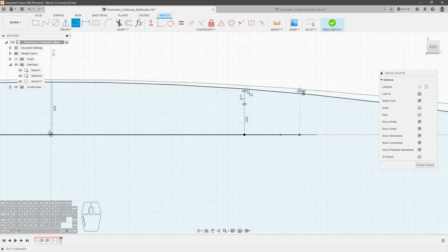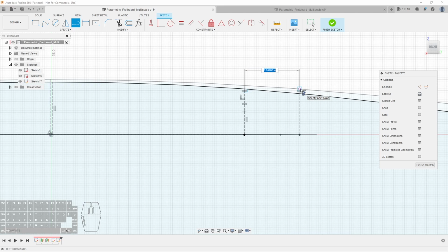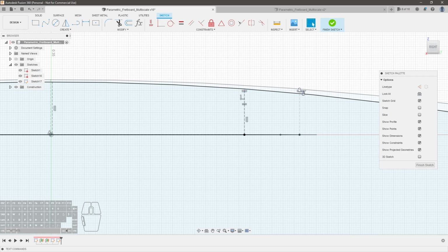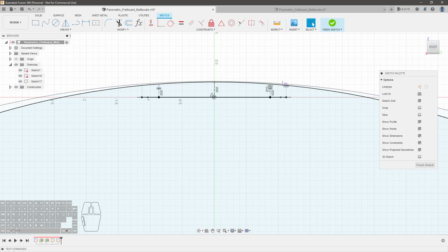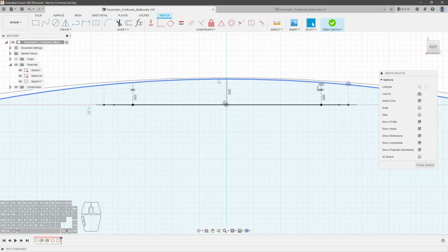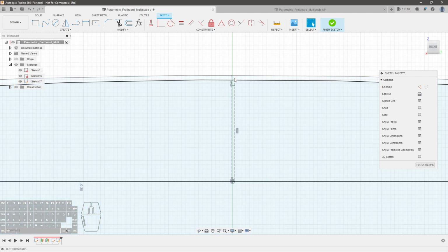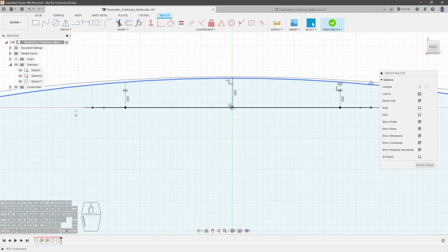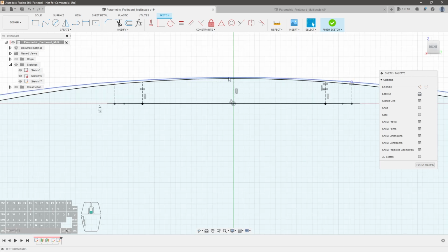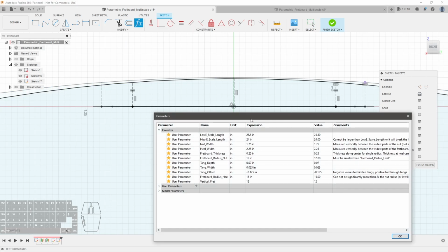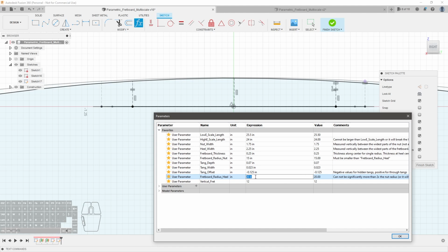And basically what that allows us to do is drag a horizontal line all the way down the fretboard, which creates a consistent thickness at the edge of the fretboard at the cost of a consistent thickness at the center of the fretboard. Now, it's not a big problem with the dimensions we gave it. It's a very small change. But as you change this dimension, so let's say like 15 inches here, that becomes considerably larger taper. Or if we make this significantly larger on the back side, so let's say 20 inches, it becomes narrower.